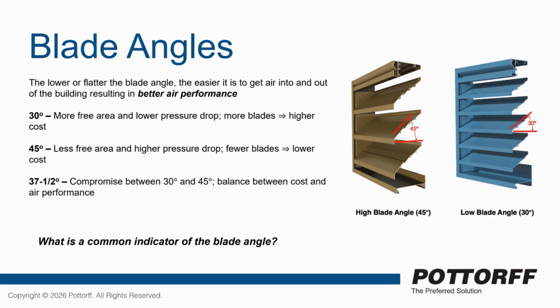The blade angles that we have here, the general rule of thumb is, and what you can see on the screen as we just talked about, we have some J and K blades here. So these are non-drainable louvers. So again, would be great for exhaust applications.